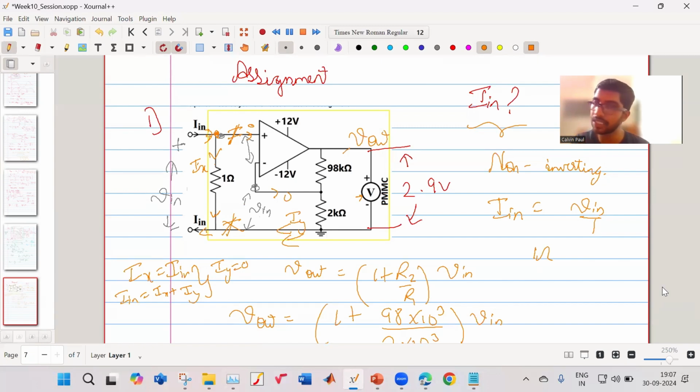It is kind of measuring current, although it is telling it in terms of voltage. Its goal is to measure current. In all the traditional circuits which you studied till now, we were using an ammeter to measure current. So what should be the internal resistance of an ammeter ideally? It should be 0 ohm.